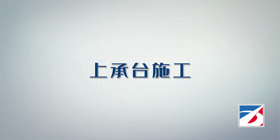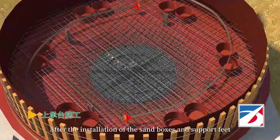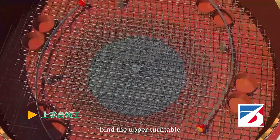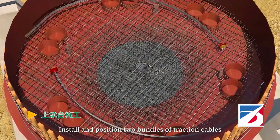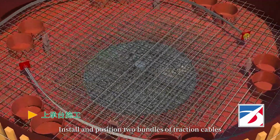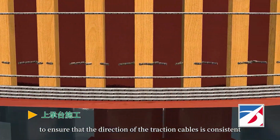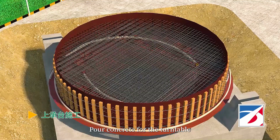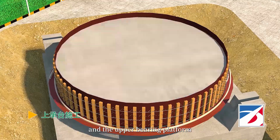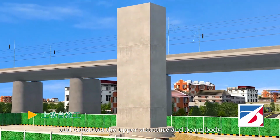Construction of upper bearing platform. After the installation of the sandboxes and support feet, bind the upper turntable and the bottom layer of reinforcement of the upper bearing platform. Install and position 2 bundles of traction cables to ensure that the direction of the traction cable is consistent with the direction of the swivel. Pour concrete for the turntable and the upper bearing platform, and construct the upper structure and beam body.